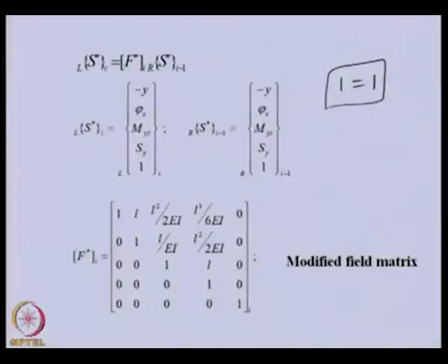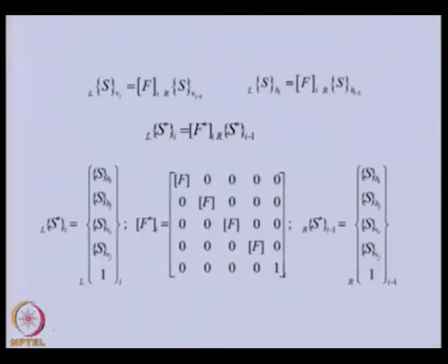So, for that case, when we are considering both plane motion and when we want to consider the damping or gyroscopic aspect also, then we need to do the following. Here you can see this is the state vector which is in the horizontal plane, these two are in the horizontal plane, these two are in the vertical plane. In the horizontal plane itself we have taken the real component and the imaginary component.